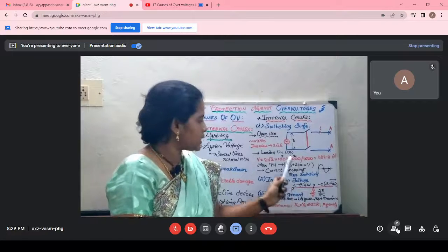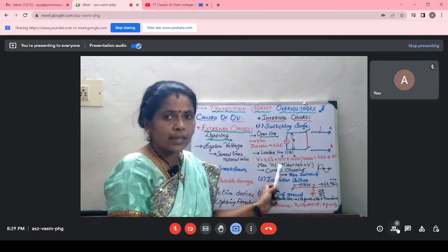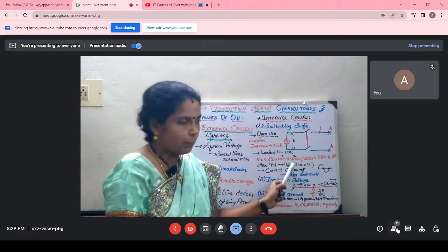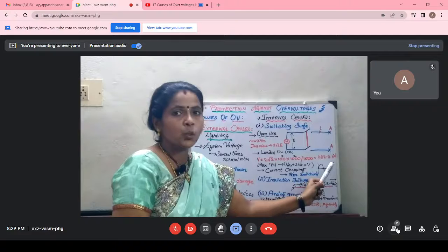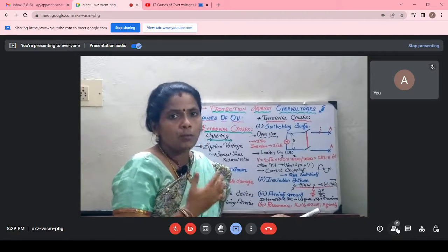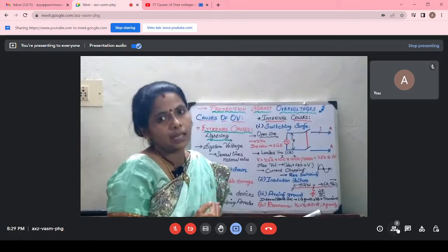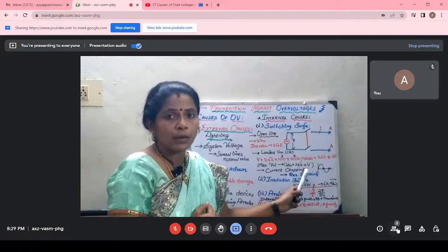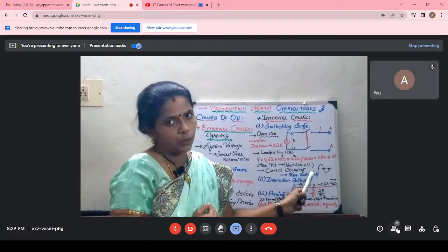In this case, the maximum voltage is the initial maximum voltage Vm plus the increase of 282.8 kV. This is quite a cumbersome value which cannot be neglected. Such a high voltage will be induced in the line, so a suitable protection mechanism is required.